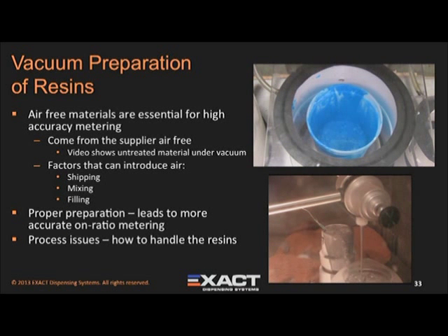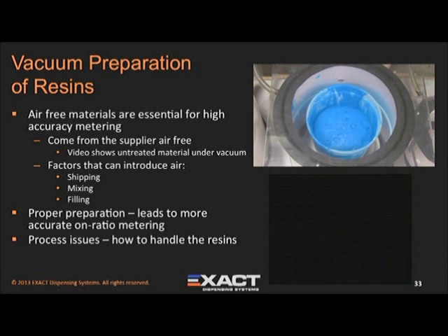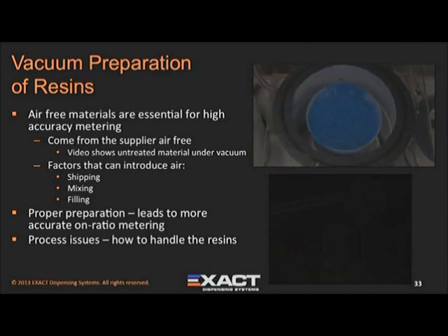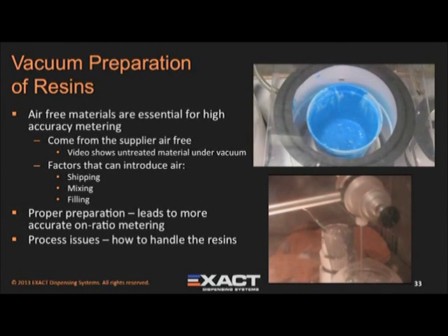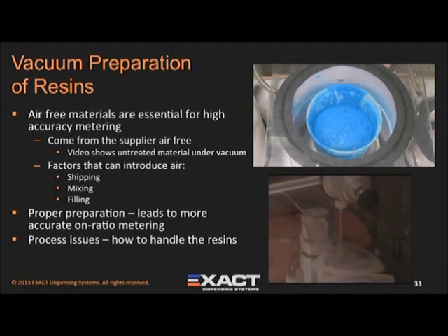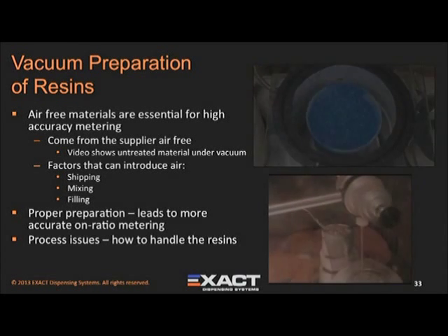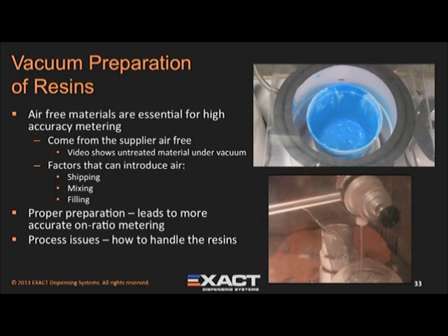Air-free materials are key to successful meter mix of 2K materials. The videos on the right side of this slide are dramatic, showing how air in the original resin can be drawn out of the resin with vacuum, but also show how much air may be in the resin in the drum. Vacuum degas before trying to meter is a great rule to follow.